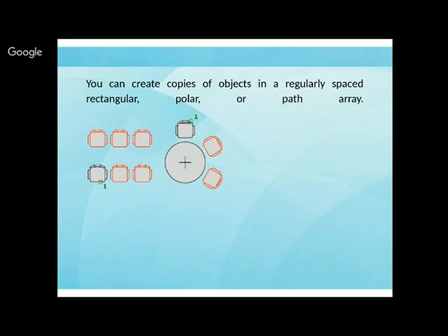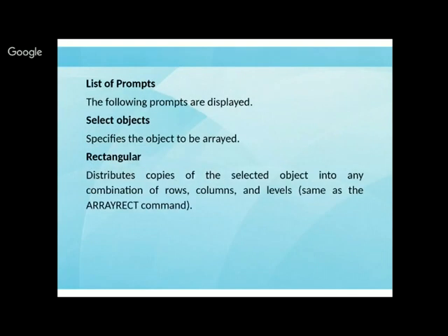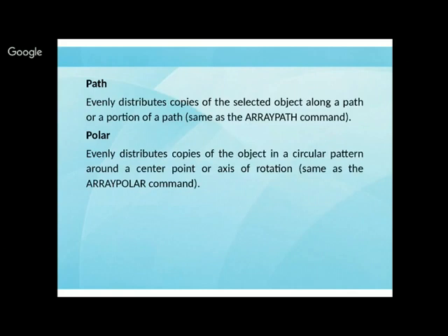The command is array, and let us see what we get when we give the command array. This is displayed, right. The fashion of it, either rectangular or polar or the path. You can array along the path also, but it is different, so we'll explain it later.